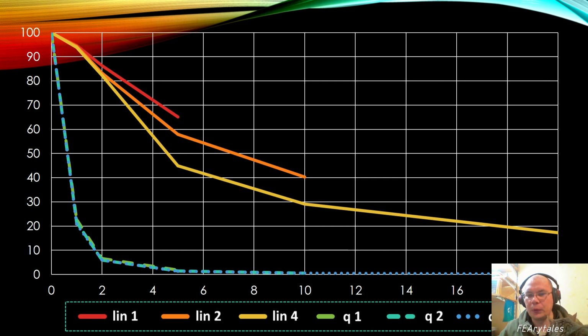For example, for explicit tasks, where in most cases only linear elements are used, tetra elements can have some benefits over hex elements, because hex elements have something like the hourglass effect, which can give some problems.